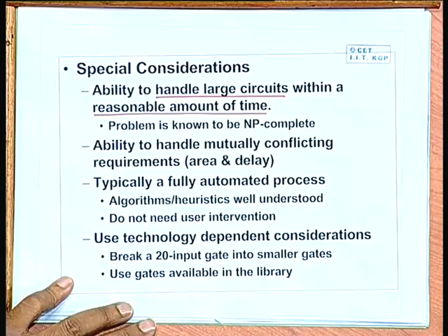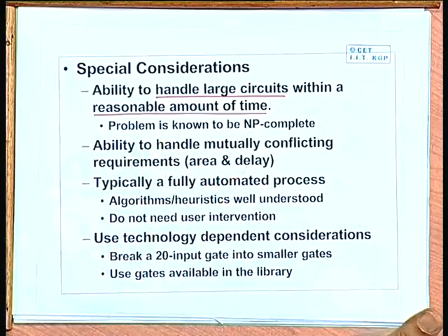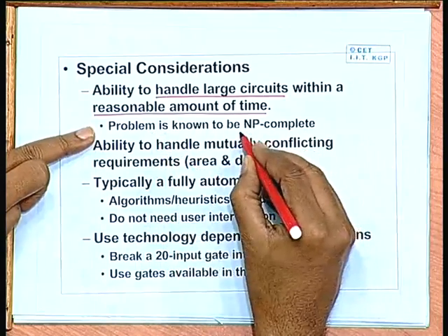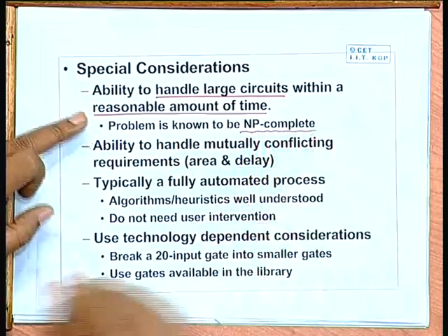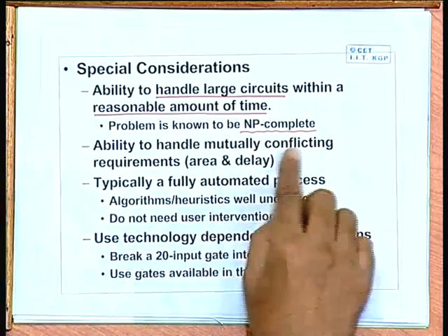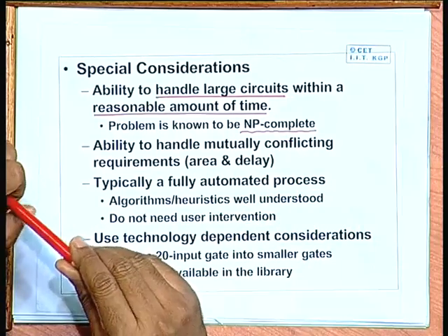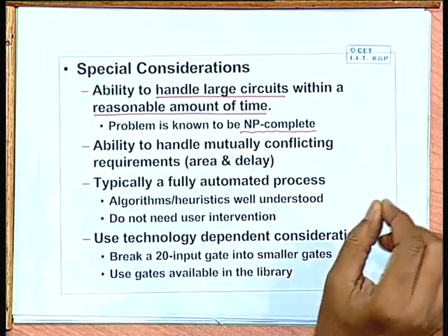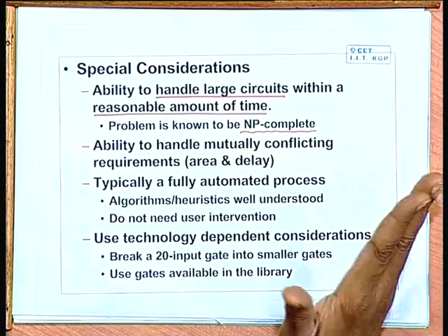But unfortunately, the problem of getting the best solution has been proved to be an NP complete one, which means that it is computationally infeasible, or computationally very expensive, to ensure that the design you have synthesized is the best possible one. So, obtaining the best possible design is not practical for large circuits. This is something which we need to understand.